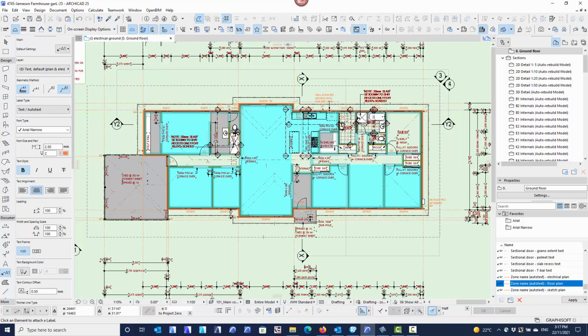Now all I have to do is label the zones, which I can do one by one, simply by making sure that my zone activates. The easiest way to do that is to use the spacebar key, which is the quick select toggle. Now you can see here it's saying multiple elements, saying a slab. That's not good. I don't want to add the label to the slab.